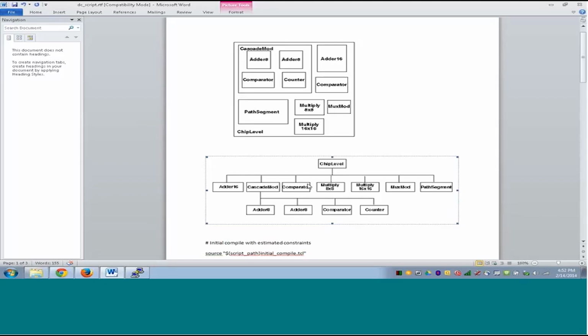Now, when I read the top level chip Verilog, I read the CPU. Let's call this a black box model. So I'll read the CPU black box model, the USB black box model, and the HDMI black box model. I will set them as don't touch, and I'll compile my chip. It will take a few minutes. My chip netlist is ready.